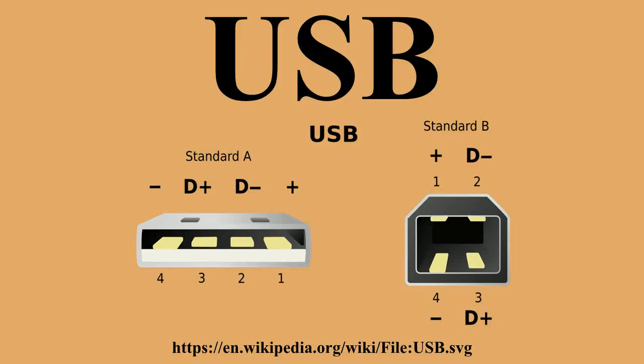However, due to the overhead incurred by 8b/10b encoding, the payload throughput is actually 4 Gb/s, and the specification considers it reasonable to achieve only around 3.2 Gb/s. However, this should increase with future hardware advances. Communication is full duplex in superspeed transfer mode. Earlier modes are half duplex, arbitrated by the host.